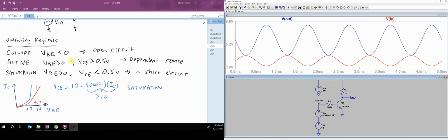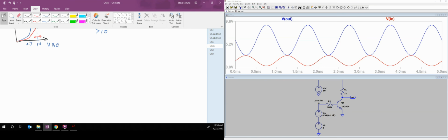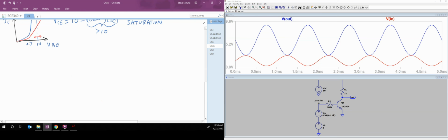So let's go over here and draw it on our sheet so that we have our final answer. This is what my final design looks like. I have a 10 volt supply, a 1 kilo ohm resistor, and my BJT transistor. I ground my emitter. I put a resistor.